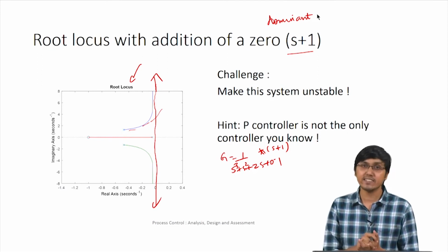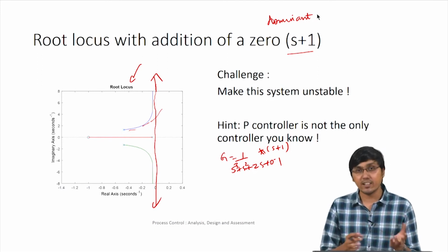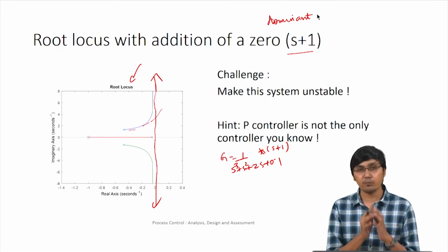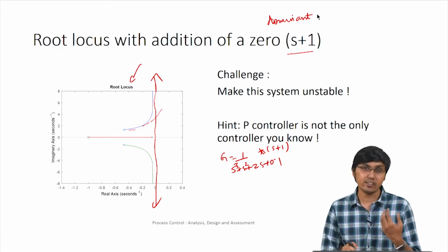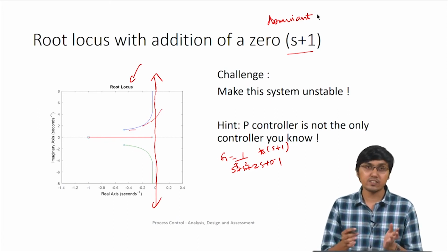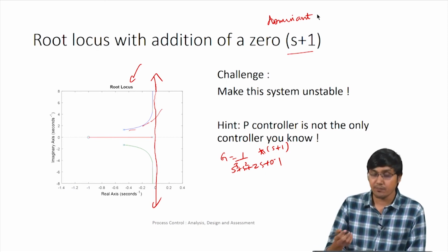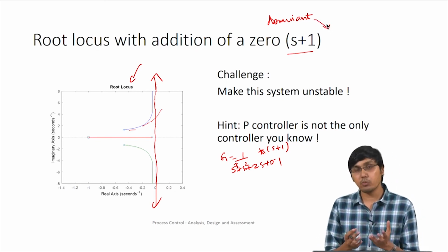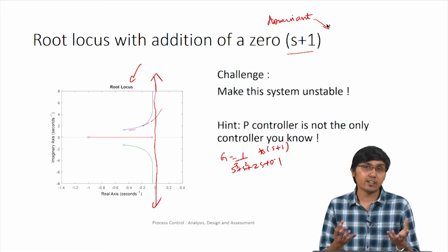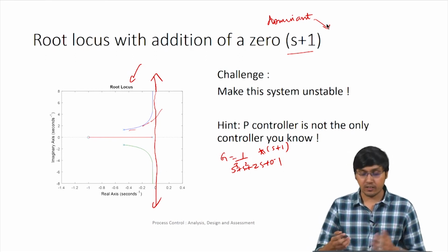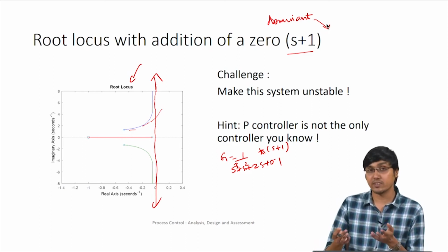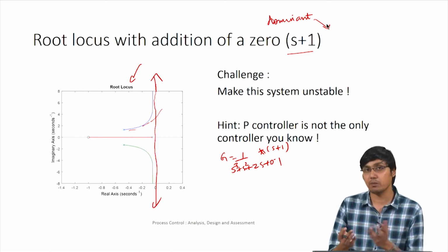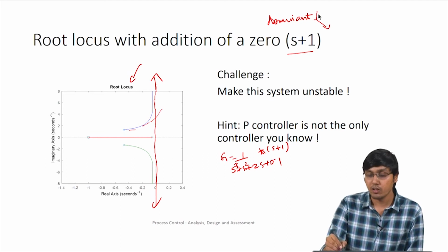We are emphasizing the partial fraction approach to understand a lot of control concepts, because we can find out most of the concepts more easily when we imagine it that way. Basically, which pole is going to have a bigger impact on the response of the system, that is what we call the dominant pole.